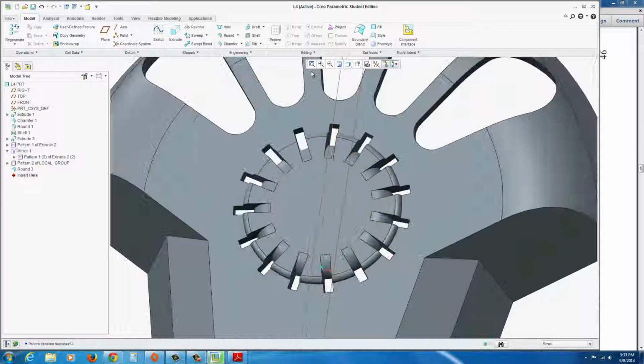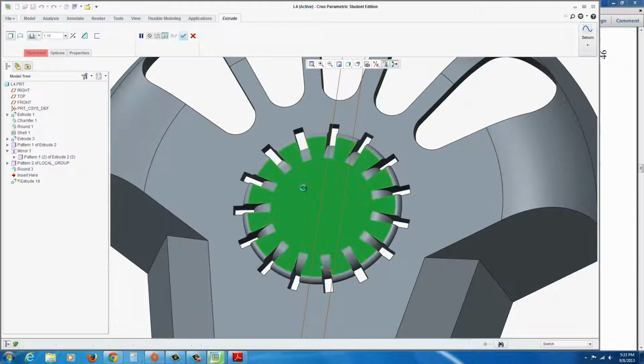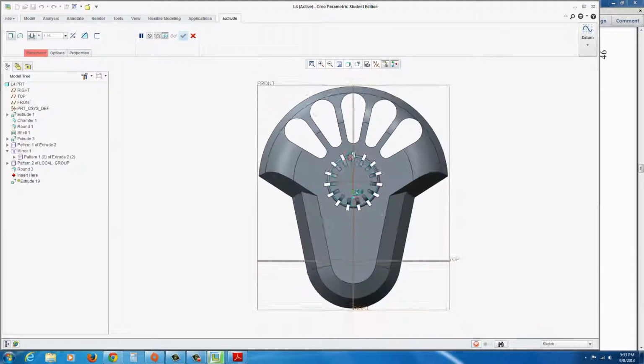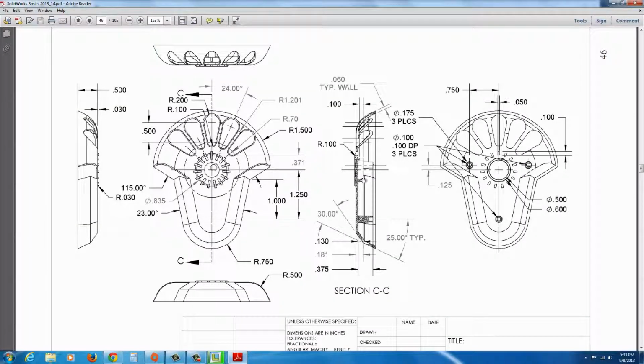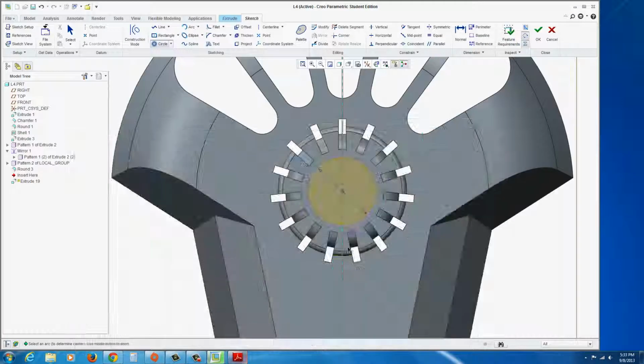There are our features. Now we'll go to Extrude and select this face, in which we could start our sketch for the diameter. We could go to Circular Pattern, or just concentric circle. Drag in a circle off that edge, double click, and that's going to need a diameter here. It's not specified because it's a logo, so we can really put anything we want in this one. So just double click, make it 0.5.